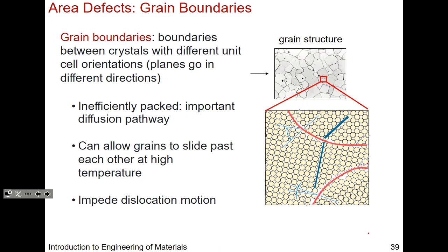And so you see here within one grain, the area that I'm outlining here, you can have this particular area where the atoms pack very nicely in some crystal structure that you would expect. And then with another grain, the orientation can change a little bit, but right at the interface here, see, right at this interface, you can see that there are gaps and also misalignment. And that's okay, because in real world systems, you have these grains and you have polycrystalline materials because that's just how materials are made.